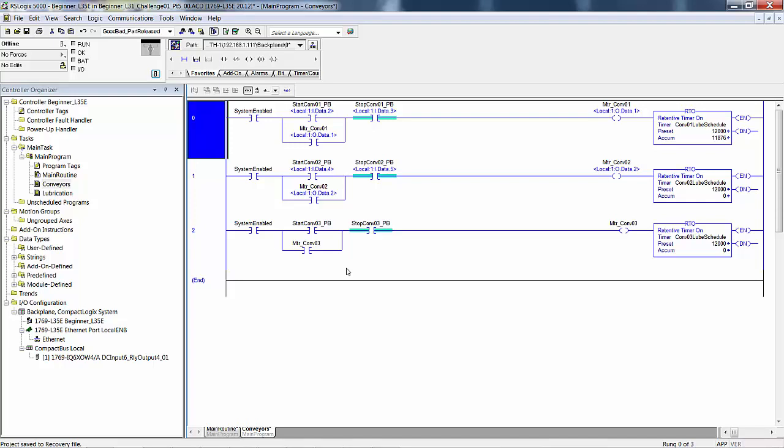Now we could have cut and pasted those 2 rungs, but this sequence is much safer, just in case you have an accident with your mouse on the way to paste them. If you cut them and then never actually paste them, you could lose them. This leaves the main routine with 1 rung of logic to enable the system. To verify what I've told you, and that's not entirely true, but we'll just follow the manual.